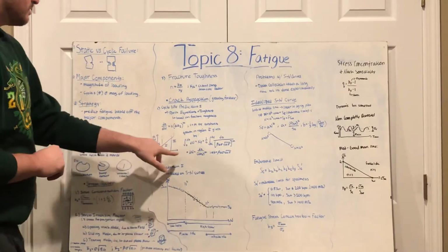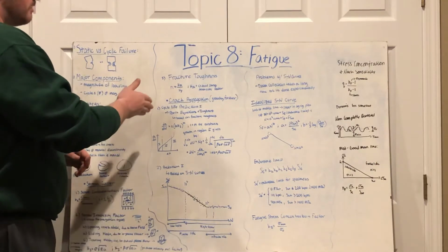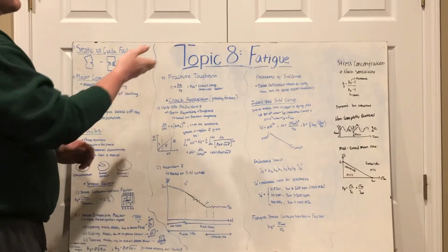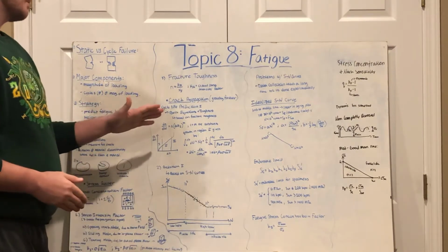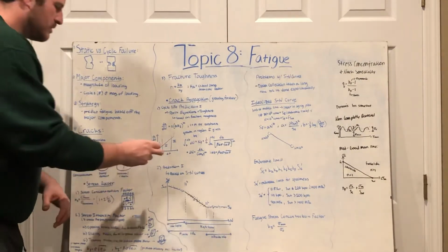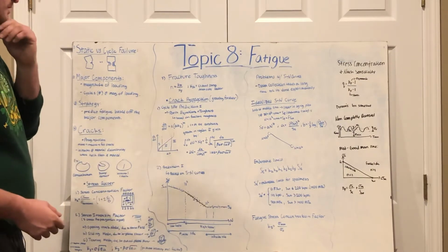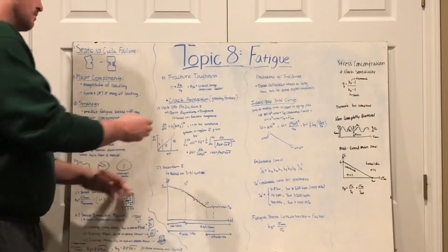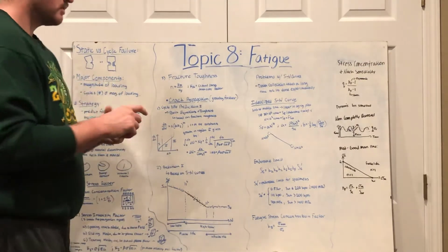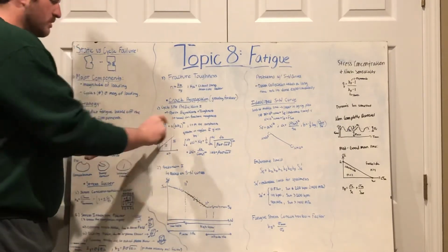And we look here at this region. This is the region of crack propagation growth. Initially it starts off in a non-linear fashion, growing super fast, and then all of a sudden it starts going in a more linear fashion, then boom, it starts going straight up again. We want to focus on this linear region since we can model that. The major region we can actually model with more accuracy is this middle, more linear region.